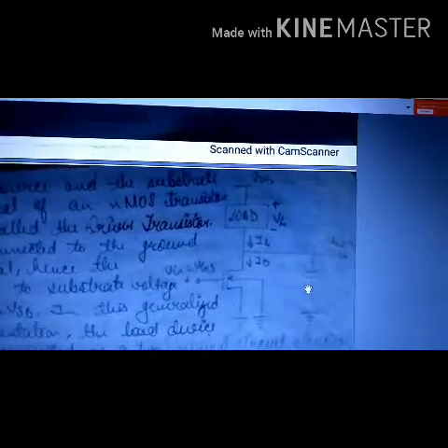Since the DC current of a MOSFET transistor is negligible for all practical purposes, there will be no current flow in and out of the input and output terminals of the inverter in DC steady state, as the gate current is negligible.